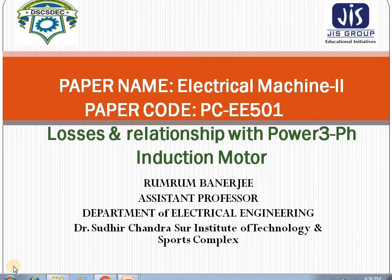In case of three-phase induction motor, the losses can be divided into parts. One part of losses occurs in the core material, another in the winding, and another in the mechanical part of the machine. The core material is made of iron, so the loss occurring in the core material is known as core loss or iron loss, which includes hysteresis loss and eddy current losses.